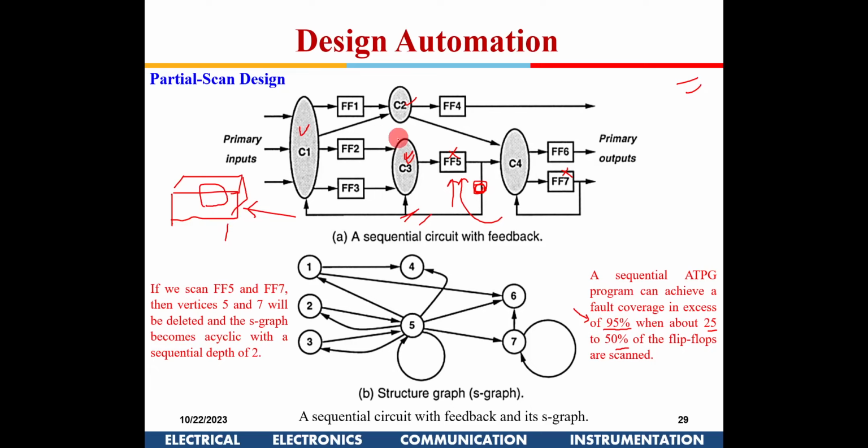So what we were talking about till now is a post-fabrication single test. But obviously once it is fabricated and deployed, suppose it is installed on an aircraft or in a car, I cannot put up all the testers and do all the tests we have studied till now, right? I can't remove the chip from the PCB and do the testing. So I have to have some test on the PCB itself every day when I'm using it. That comes under built-in test, and that built-in test does that function. So it is another offshoot of design for testability.